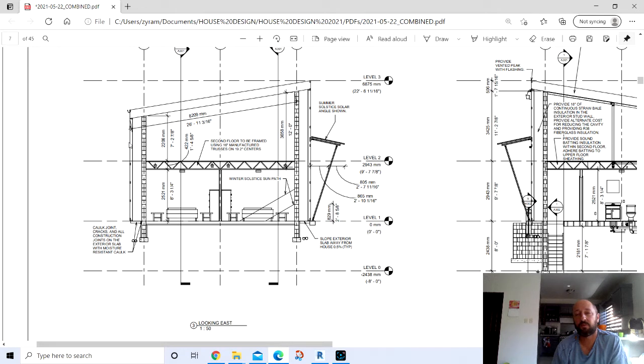Another reason was because there's not a bunch of valleys and peaks. Those are places where roofs will leak. Architects like to, and I shouldn't pick on architects, but architects like to add them because they add architectural appeal to the house, but they also are a place for leaking, and they're also more expensive to install. And the last reason I can think of off the top of my head, there were probably other reasons, is the slope.